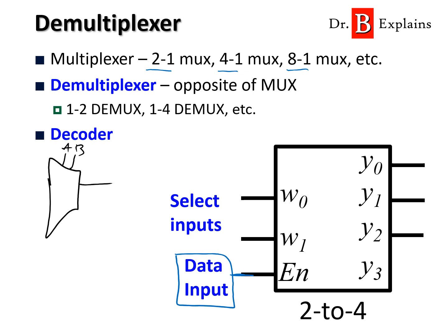Now we're going to use a 2 to 4, with select inputs A and B, for example, and depending on A and B, we have outputs 0, 1, 2, 3. So I'm going from 1 input to 4 possible outputs. Let's say I have an input value of 0, and I want to pass it to one of these 4.